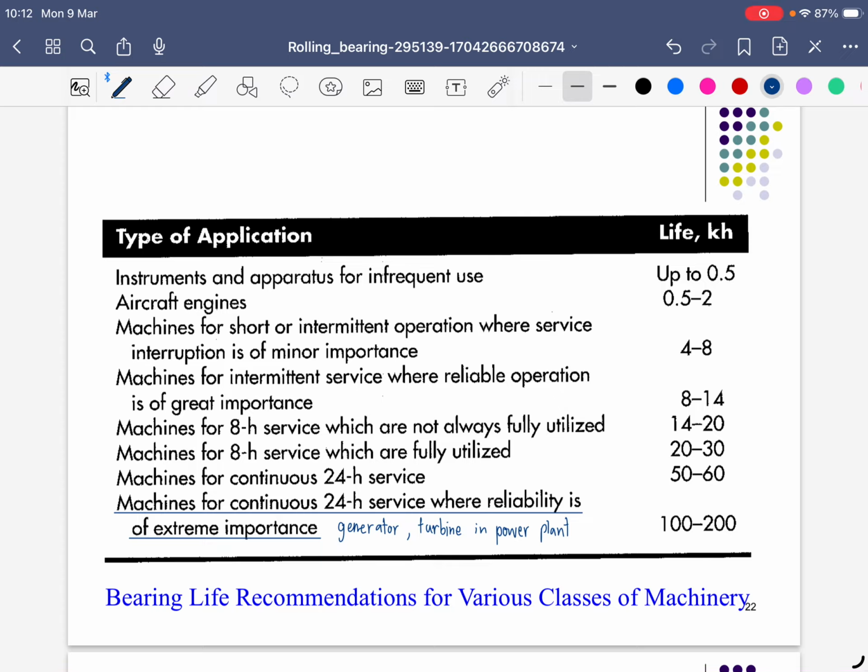But now they use a monitoring technique, by vibration measuring. When you see the bearing has symptoms showing it will fail, maybe in the next not more than 1 month, you have to decide now to change it. You order the bearing first, and then stop and change it. That may take only about 2 or 3 days, not waiting for 1 month.